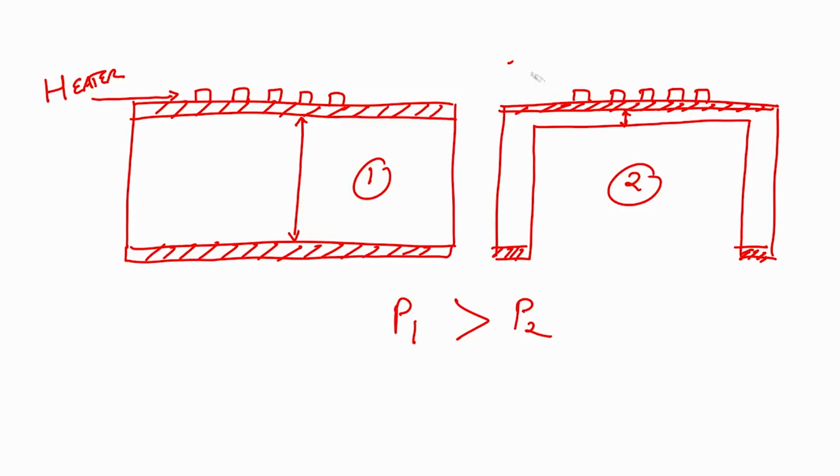Now what is the case? Once you have a heater, you need a sensing material. So, on this heater, because it is bigger, I have to have an insulator, an insulating material, let us say this is SiO2. On this insulating material, I can have my interdigitated electrodes.